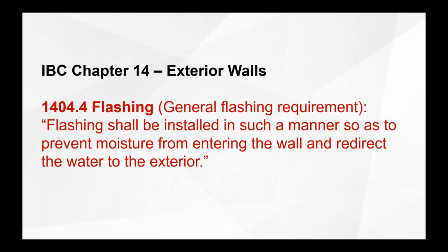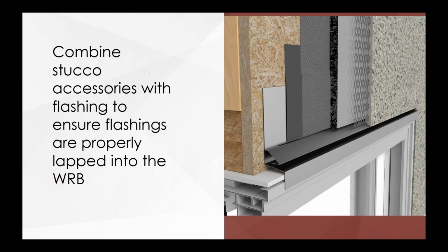And I kind of cockily said, with confidence, I said, because it's not flashing. He goes, oh, so it let the water in. That's exactly what happened. I walked right into it. He took this part of the code and used it to his benefit, and it was the right thing. Flashing is supposed to redirect the water to the exterior. So think about it. Even your stucco accessories should redirect the water to the exterior.